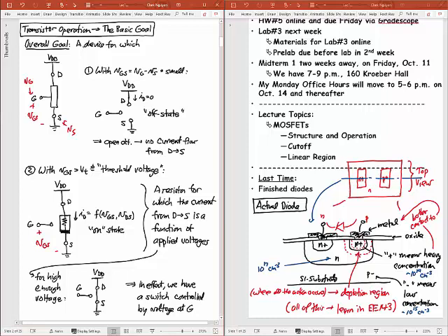And if I can change the value of that resistance based on VGS, that means I can regulate the current flowing from D to S, provided VDD stays constant. I can regulate that current just by changing this resistance value. And this resistance will not generally be linear with this voltage. It will be some function of that voltage that's going to be nonlinear in this case for this transistor. For any transistor, it's generally nonlinear.